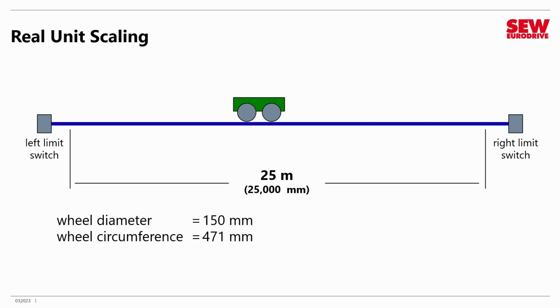However, what if there's a gearbox in the picture? As we know, gearboxes slow the motor down, therefore they increase the number of turns you need to rotate to go the same distance. Well, we'll say that we've got a gear ratio of 7.12. So you very roughly have to turn that shaft about 7 times as much as you think you do to move 471 millimeters.